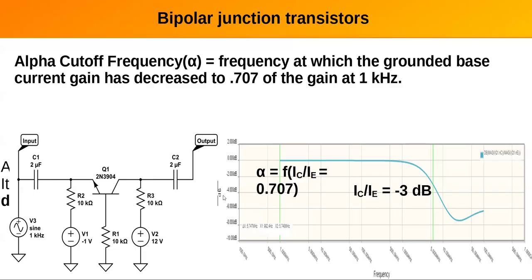It's just like a grounded grid transmitter tube. That grid is not always connected directly to ground. It usually goes through a little parasitic LC and or resistor. So what's going on here? It's a one-to-one current amplifier, but it's also a voltage amplifier.